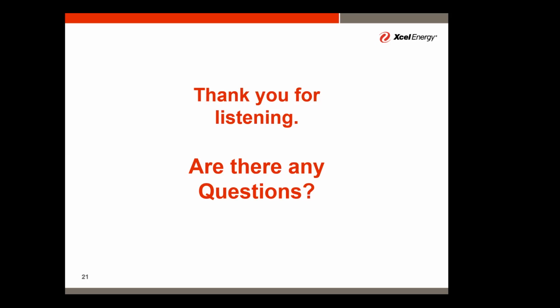Great, thanks. And then I guess some other flags that I think we've seen utilities use when looking at results would be discrepancies in the number of line sections, and loading and voltage violations, and equipment settings that might vary from those commonly used. I think that's appropriate to talk about at this stage. Maybe some of those are appropriate to talk about at earlier stages for validation. But I'm curious if Xcel is looking at any of those before publication.